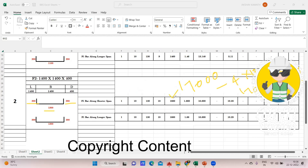1660 divided by 1000 will give me 1.660 meter. And now coming to the number of bar. So how do you find it? The number of bar will be the total cutting length of one bar, you multiply this by number of bar, that is 10, and this you multiply by number of footing. So 1.660, if I multiply this by 10 and by one footing, obviously it is 16.60 meter. Got it? Same thing here also it follows.